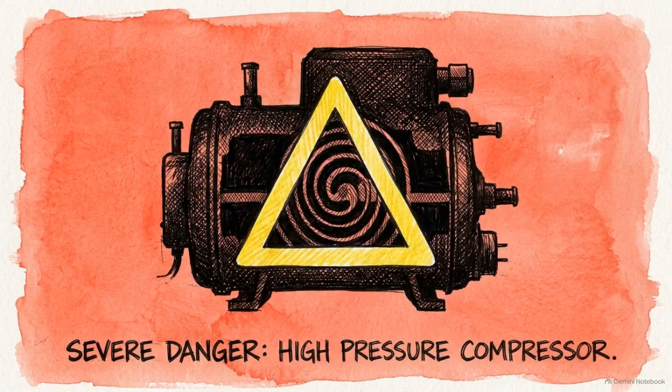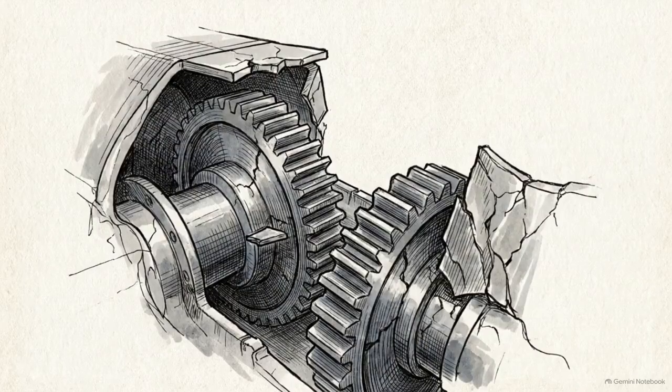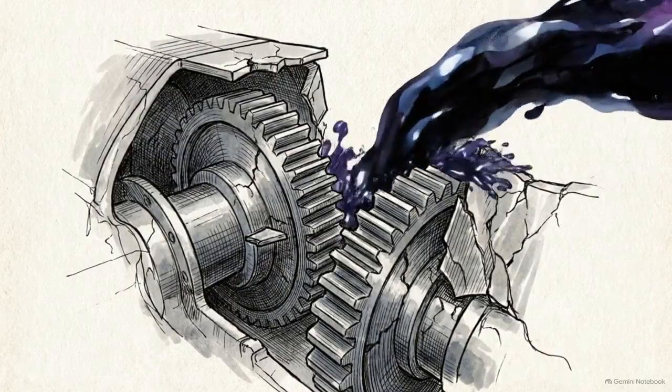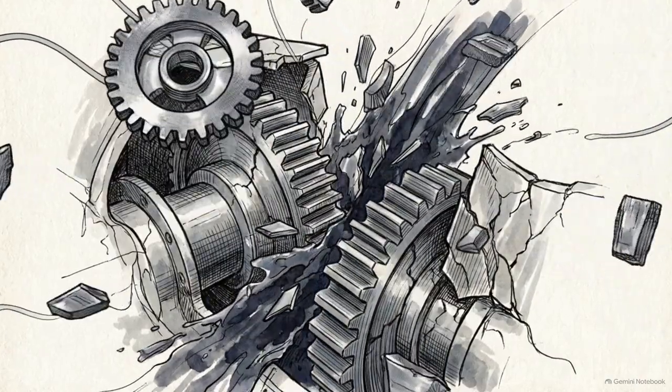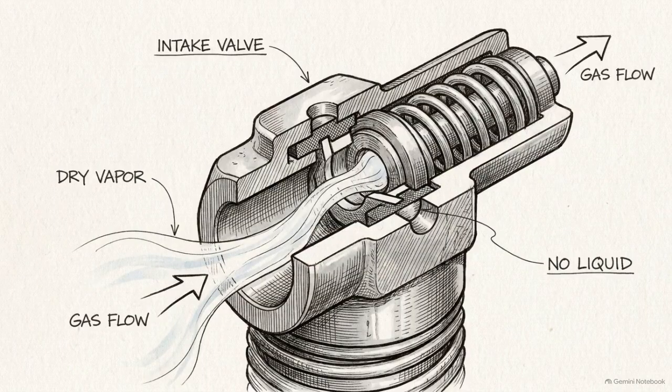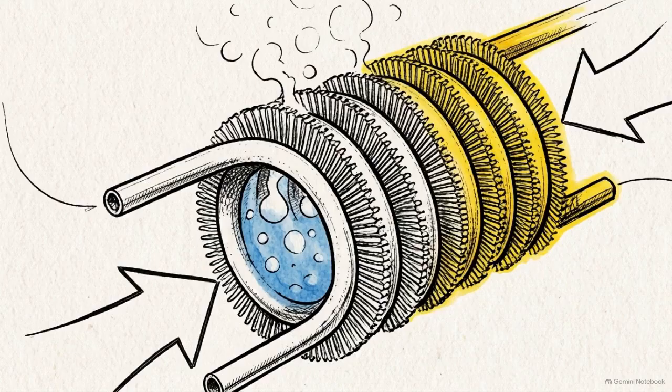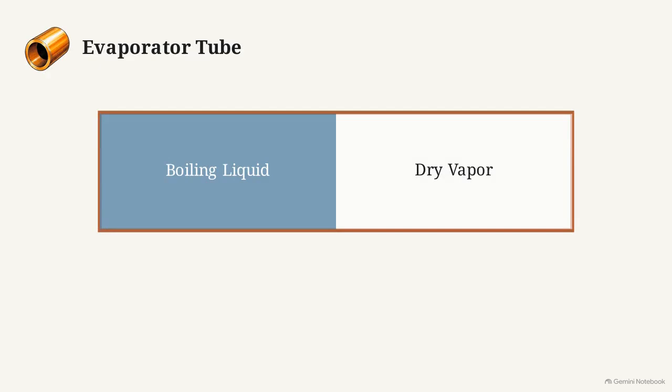This optimization carries a specific mechanical hazard. Because liquids are incompressible, any refrigerant that fails to evaporate before reaching the compressor can cause the internal metal components to deform or fracture under pressure. Because compressors are designed to pump gas, not liquid, complete evaporation inside the coil is non-negotiable. To ensure this, engineers enforce a strict thermal safety margin called superheat. Superheat is the measurable difference between the actual vapor temperature leaving the coil and the underlying saturation temperature.